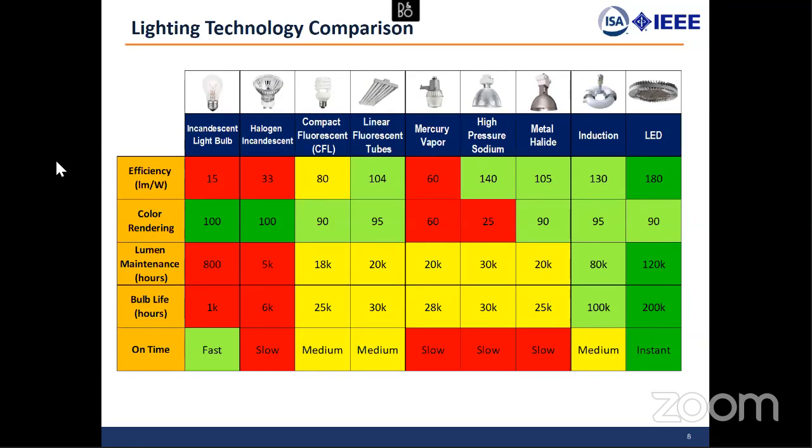There's a derating factor that's built into the program. When you choose an LED light source, it's just derated to reflect how many lumens you're trying to put in the space. For high pressure sodium, we're using like a 0.7 factor now; LEDs use like 0.9. There's a variety of different derating factors written into the software. But when you're doing comparisons against older technologies, you can get out of whack.